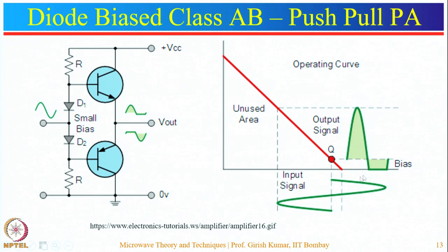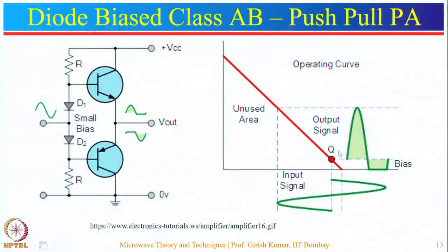The conduction angle of these amplifiers is slightly greater than 180 degree. It depends upon the biasing situation. So it could be of around 200 or 220 degree. Here you can see for this much of duration the output signal will appear in these cases. So the applications of these class AB amplifiers are that they can be used in the jammers or signal enhancers and in many other circuits wherever high power is required and efficiency is also one of the considerations.